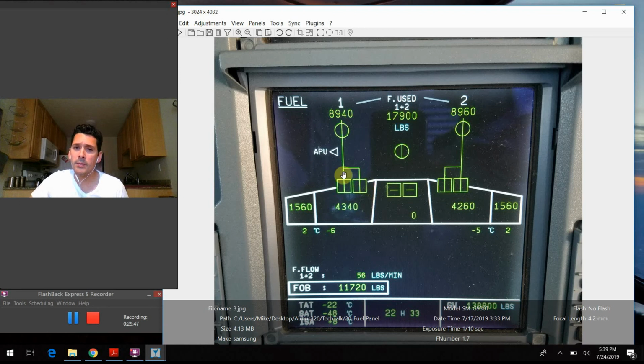And if you want to break this down and talk about exactly what's happening in each of these situations: because all these pump icons are green right here, it means the switch is in the on position. But if you look at the dash in the center tank here and the line in the main tank here, you can see these are oriented in a vertical fashion. These are horizontal. These just mean that the switch is still in the on position, but it's not pumping anything. There's nothing coming out because obviously all the fuel has been used from the center tank, and there's no need for the pump to be operating. So it just tells us that these guys are actually pumping here, and these ones are not doing anything. So just a little more breakdown of the symbology there.